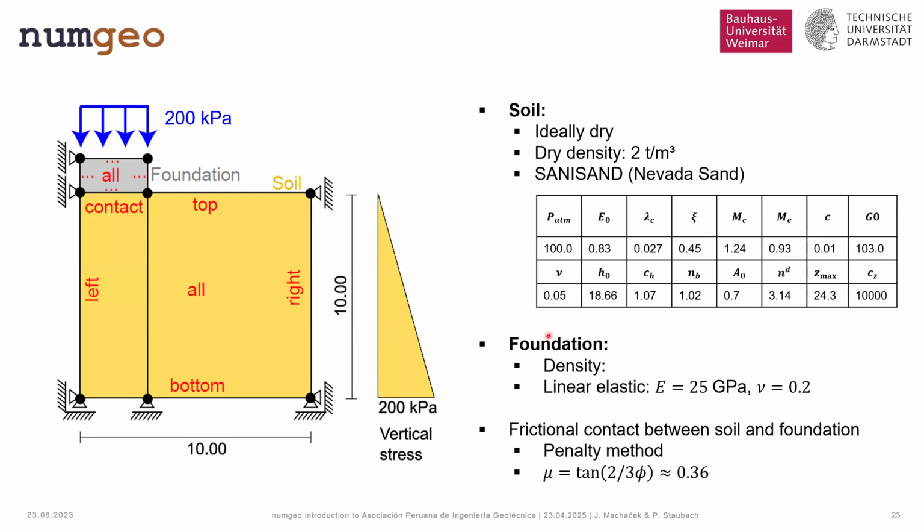Now, the foundation has the same density. I'm sorry, I'm missing the density here, but for simplicity we used the same density as for the dry soil, which is obviously not that realistic, but compared to the 200 kilopascal external force, the self weight of the foundation is not that relevant in the present case. The foundation will be modeled linear elastic with a Young's modulus of 25 gigapascal and a Poisson ratio of 0.2.